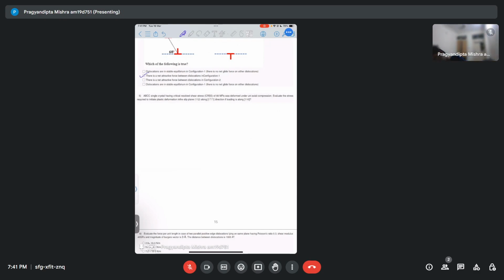So cos phi would be between 110 and the 112 slip plane, right? Yes. So on top it will be 1.1 plus 1.1 plus 2.0, divided by a denominator that will have root 2 and root 6, right? So this will be 2 divided by root 6. So let's just keep it like this only.